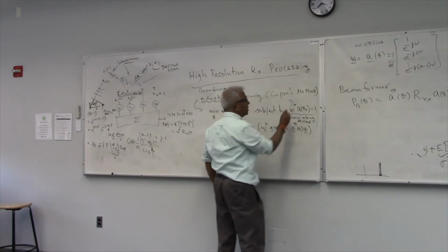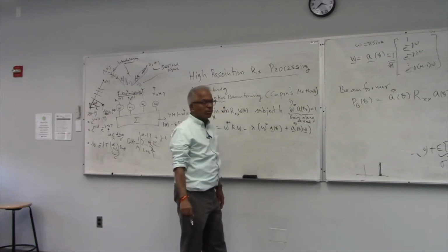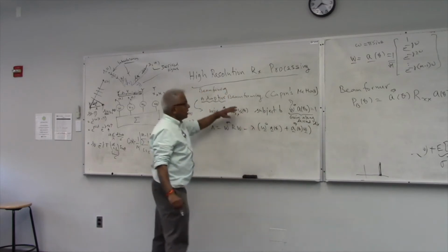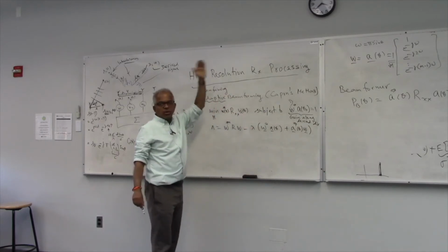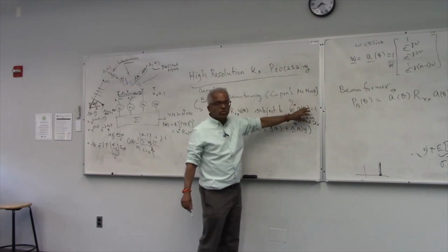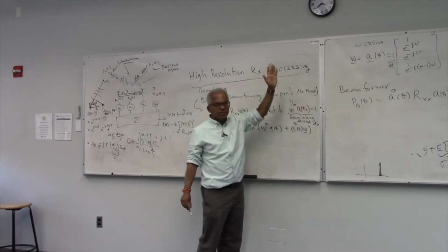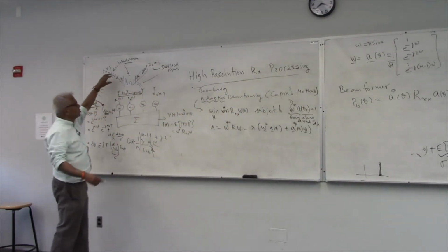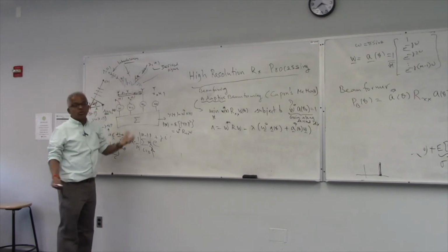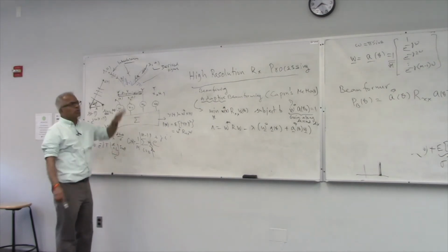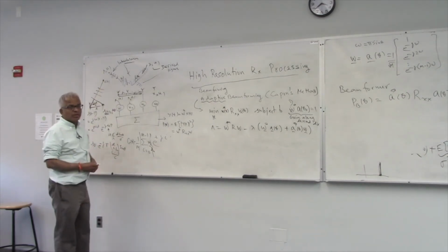So you're trying to find the weight vector W. Maintain the gain along the desired direction to be a constant, and at the same time minimize the output power. You can see that if the source is along this direction, that direction is unhurt because I'm keeping it constant. So the only way to minimize is, by logic, minimizing the contributions from the unwanted signals or the interferences. That's the idea. You are approaching this in an indirect way.